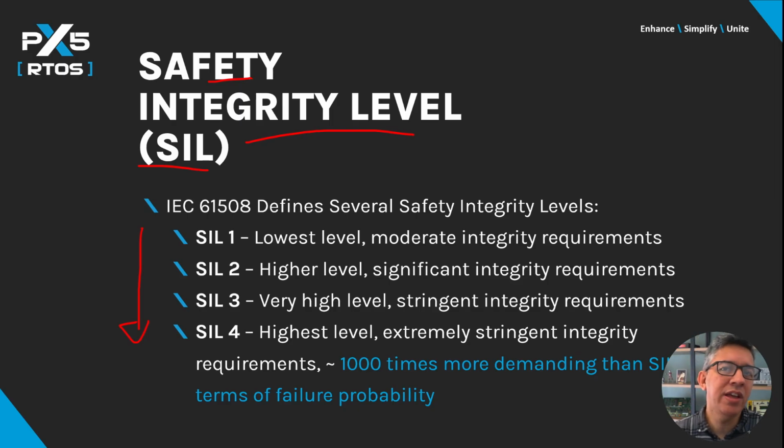If the device failures could contribute to injury or equipment damage, but the damage is not catastrophic, SIL 1 might be applicable. Another example is an overflow sensor, which could be SIL 1 if this overflow only causes cleanup and downtime expenses. On the other side of the scale is SIL 4. This level is reserved for safety-critical devices where a malfunction can result in catastrophic events.